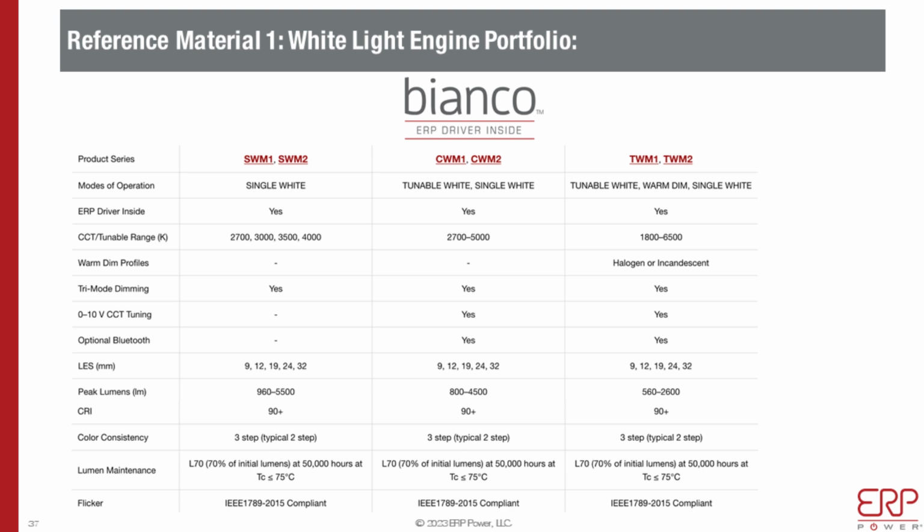But also, whenever you bring in AC, at some point, per electrical code, there has to be some protection there. You remember on the last one, what I call the pendant module, we still had a little bit of a canopy area, basically to do the wire nut or whatever connector, Wago or whatever is being used.